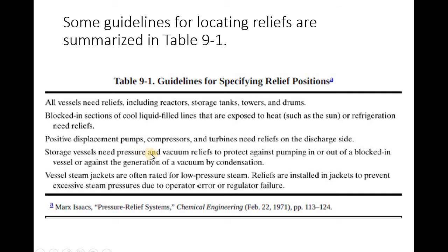Storage vessels need pressure and vacuum reliefs to protect against pumping in, because for storage you're pumping in liquid, right? You're pumping in gas, so you need to protect it from any blocked-in condition, from any blockage, and you need to be careful about this storage vessel.